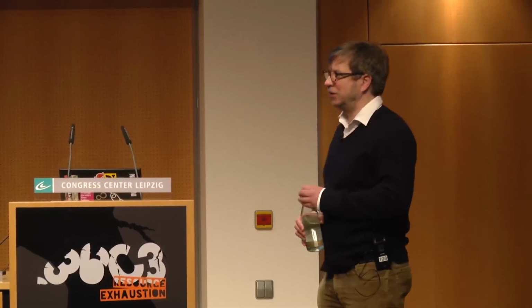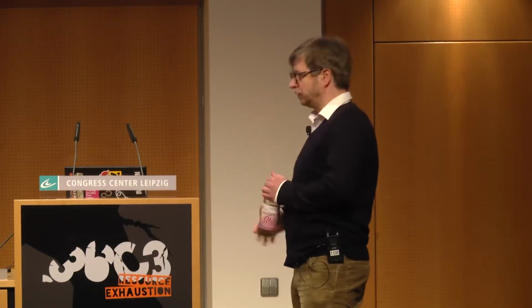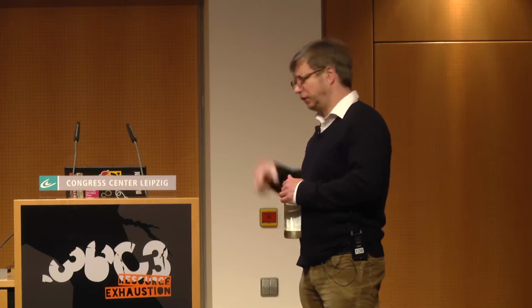One more question. What's the size of such a transistor, and aren't they quite slow then? Okay, we start with 1 micron. So the length of the channel between drain and source is 1 micron, 10 to the power of minus 6. The width is 1.5 micron. So that's the size of the transistor.